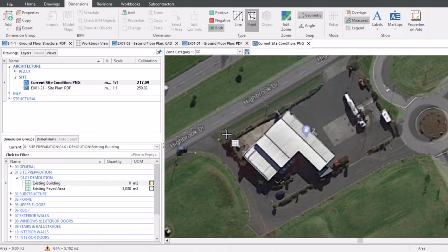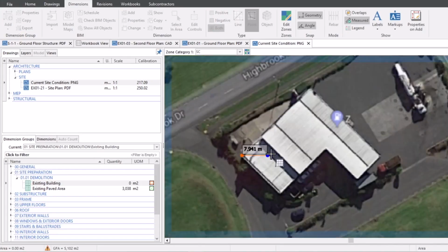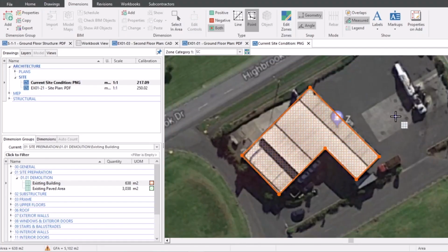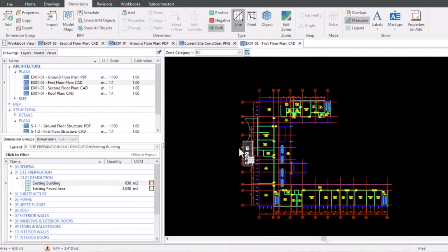If required, we can turn our angle snap button on. This means that when we extend the lines out to the next point, they snap to incremental angles of 15 degrees, just like this. We can also turn on point mode instead of line mode for a DWG or PDF if required. We can also turn this function on while in line mode instead of point for our DWG and PDF files if preferred.